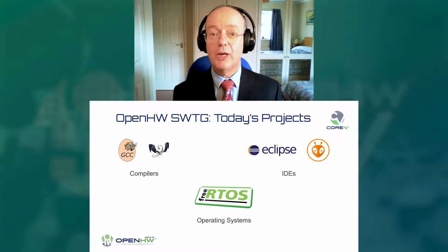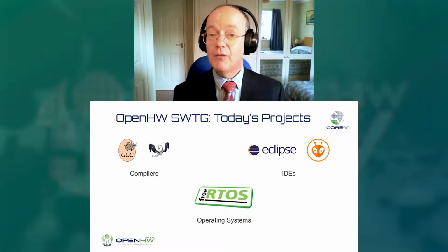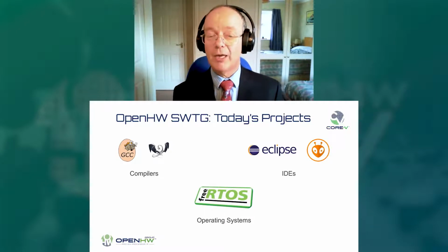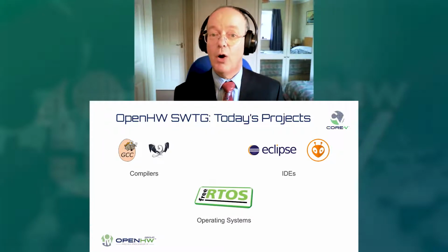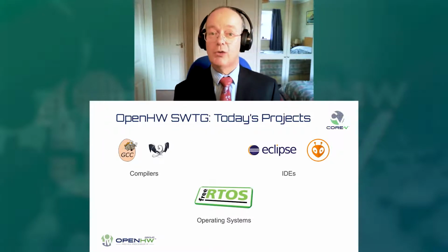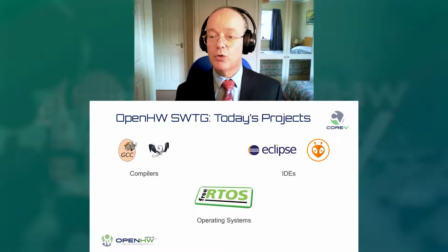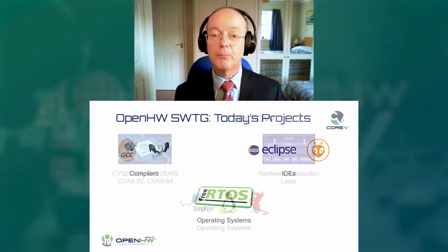These aren't our only projects. We have others in progress. In particular, we have quite a lot of work going on providing software models for the software engineering team so you can develop your software before your silicon chip's ready. We have OVP Sim from Imperas to provide you with high-speed models, and for those who need more accurate models, we are developing Verilator models for cycle-accurate modeling of the chips at the low level. And you'll hear those referenced later on during the talks we have in progress.